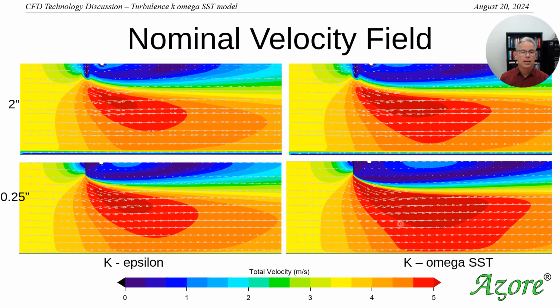But in general, the bulk flow field follows a very similar trend. Basically, the solid surface diverts the flow, it accelerates and goes around. So there's some downward motion here. And then there's some acceleration because you're kind of pinching off the flow, so the flow has to get higher based on conservation of mass. And then you have a secondary eddy that forms on the back side of this plate. So that's kind of the general flow structure that we're going to look at.